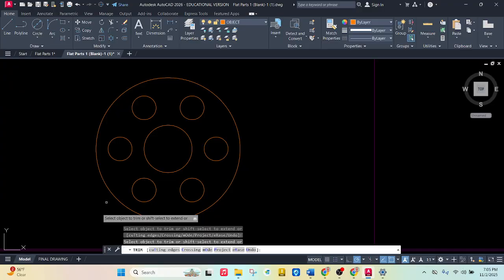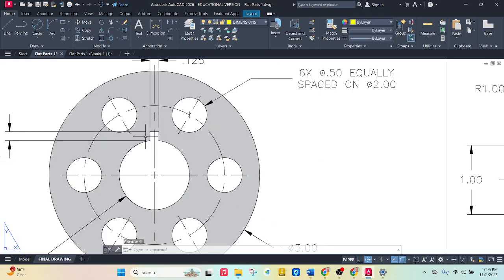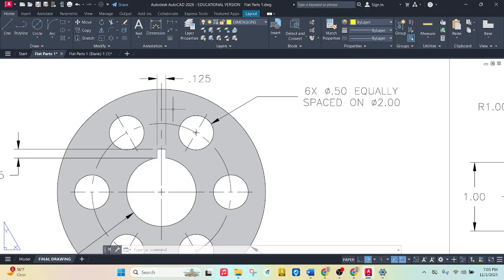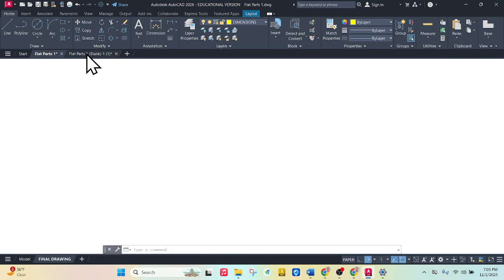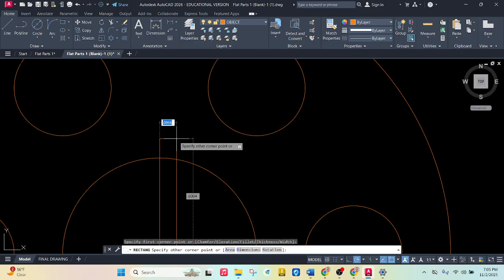And then our last little item of business is the little notch that's been taken out right here. So this one's a little hard to draw. What I'm going to do is draw a little rectangle that goes up, just a really thin one using the corner here, and then a line that goes over and chops it up. So it's 1/8 of an inch, so we're working with really small numbers here. So go back to that. I'm going to do a rectangle tool. I'll click on my corner here, and I'm going to draw half of this. So half of 0.125 is 0.0625. So that's the width there.